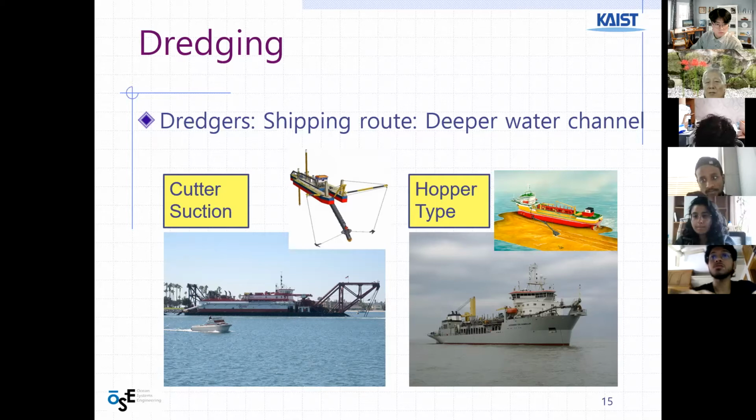For the big ship, say, we learned about the depth of the ship and the draft of the ship last time. Draft is the submerged depth of the ship. The big ship may have a 30-meter draft. Then the water depth should be at least 40 meters, right? Because the submerged depth or draft is 30 meters, then we need to have a 10-meter allowance. So a 40-meter depth is required for the passage of the ship.